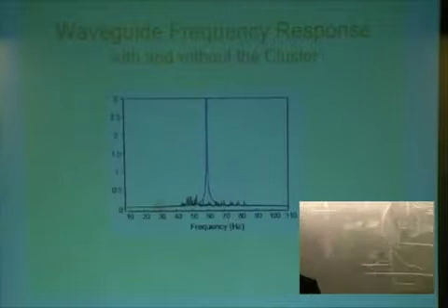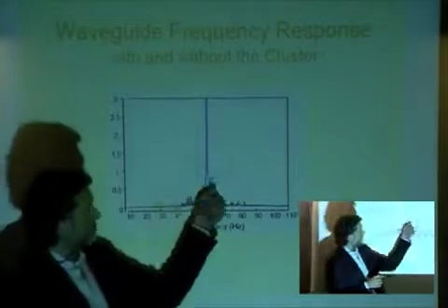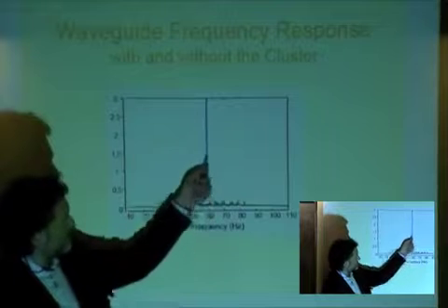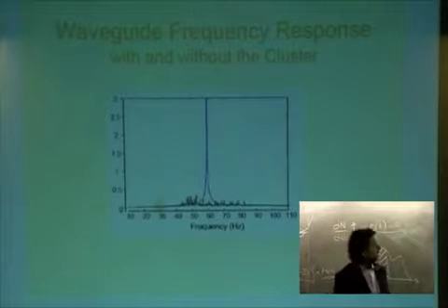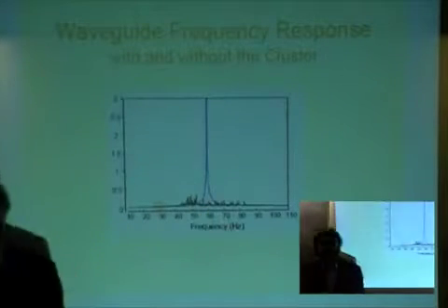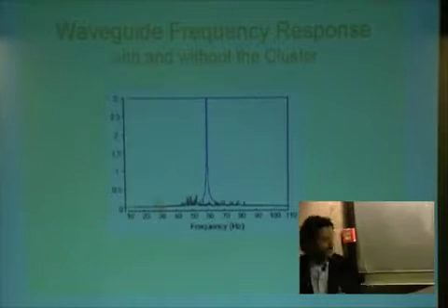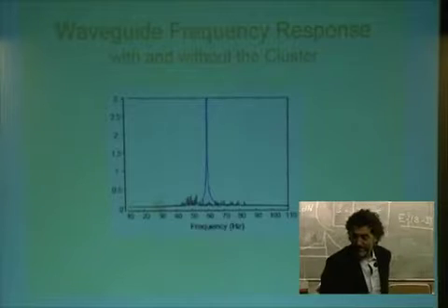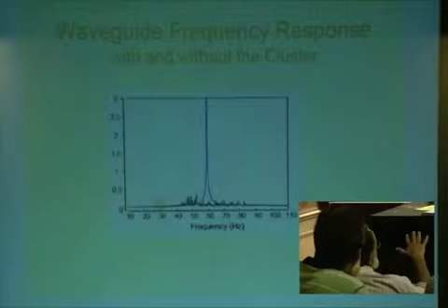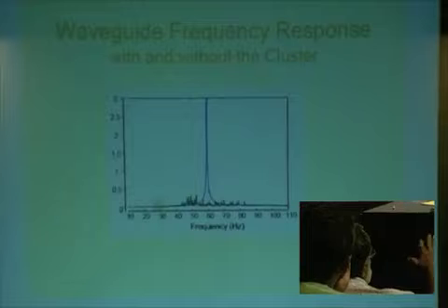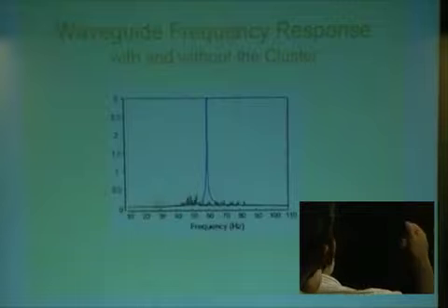And this is the comparison: this is the frequency response function before the cure. So it is the blue line. It is the impulse response of the T-beam without the microbeams. Once you introduce the microbeams, this is the impulse response of the system. So you see how it acts as an effective damper. In this experiment, you certainly increase interaction with the air, since you put 100 of these beams, so there is additional damping.